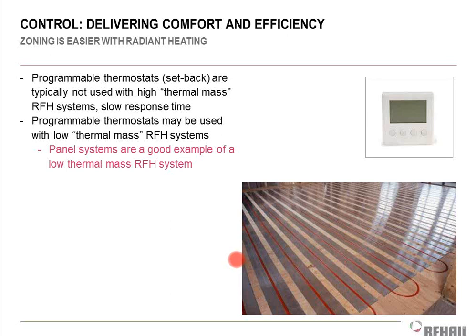But the other thing is that when you start heating one of these floors up, especially a concrete radiant floor, which is what most of them are, right, it may take 8-10 hours to get this floor heated up. And it takes 8-10 hours to cool this floor down. So someone trying to set their programmable thermostat is never going to get it right, and they're going to abandon it almost immediately anyway.